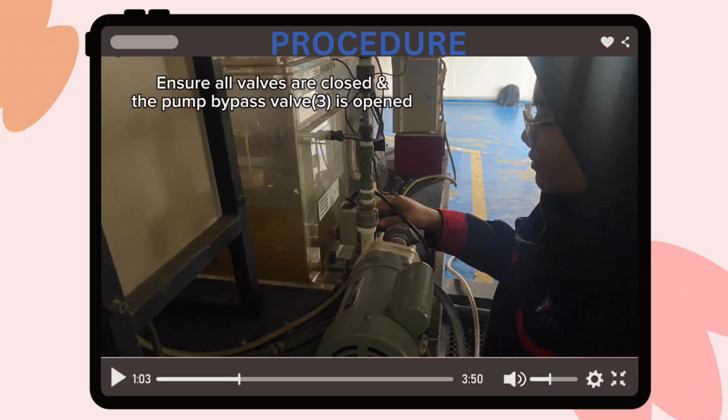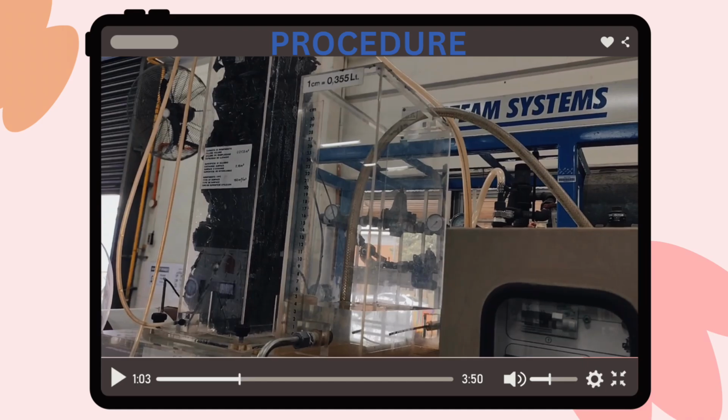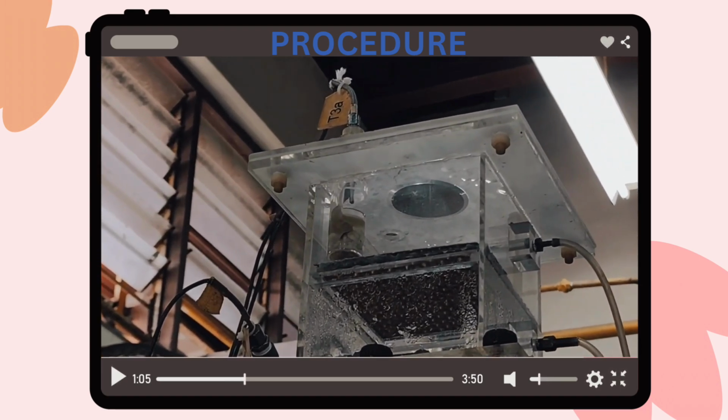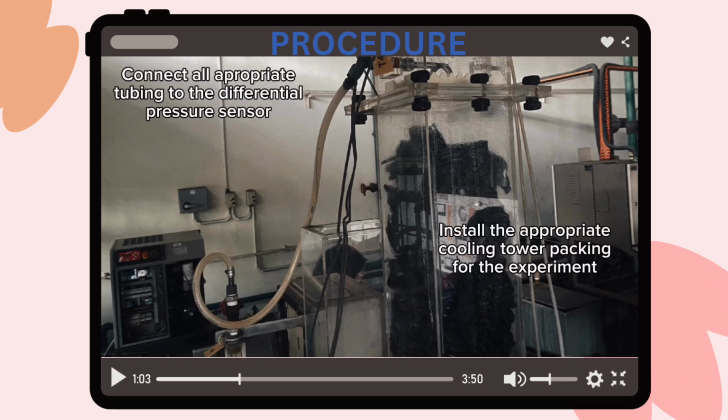Ensure all valves are closed and the pump bypass valve 3 is open. Fill the load tank with distilled or deionized water up to 30 cm on the level scale. Add distilled or deionized water to the wet bulb sensor reservoir to the fullest. Connect all appropriate tubing to the differential pressure sensor. Install the appropriate cooling tower packing for the experiment.